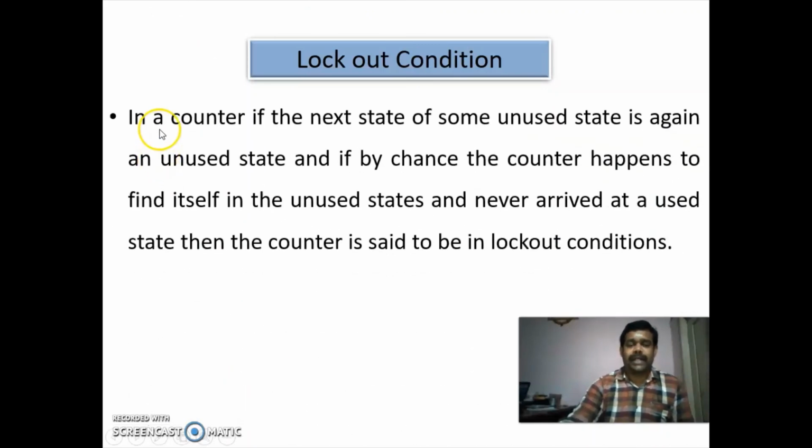So in a counter, if the next state of some unused state is again an unused state, and if by chance the counter happens to find itself in the unused state and it never arrives at a used state, then the counter is said to be in lockout condition. So what is lockout condition?